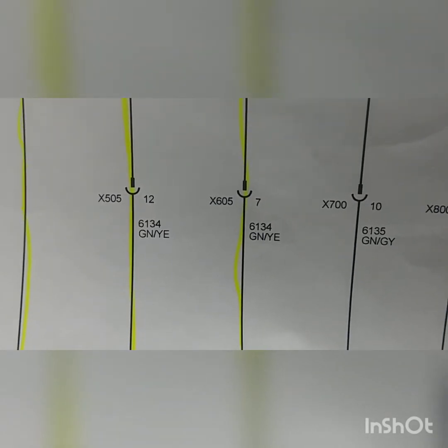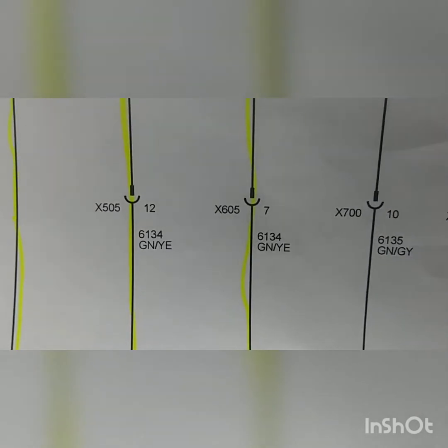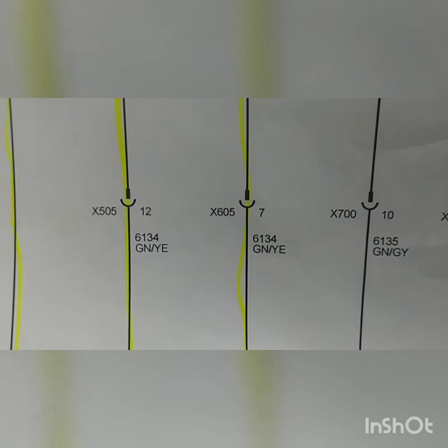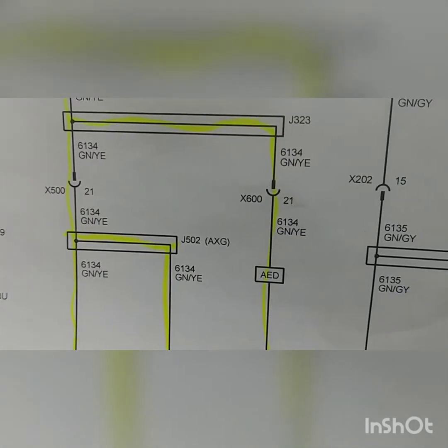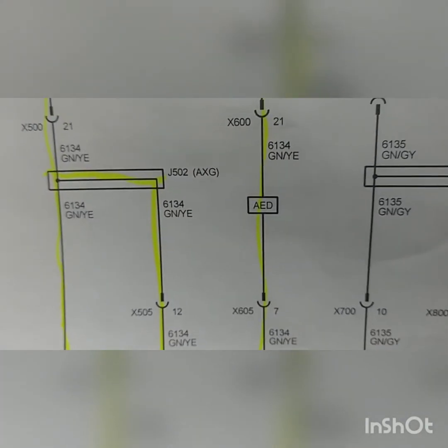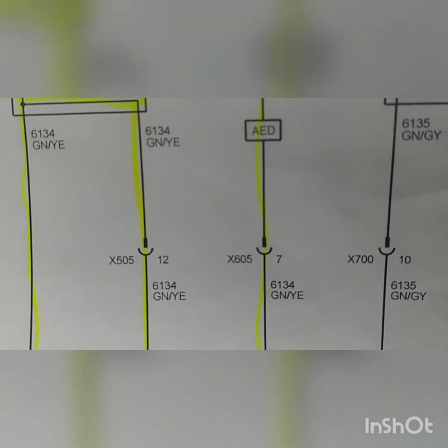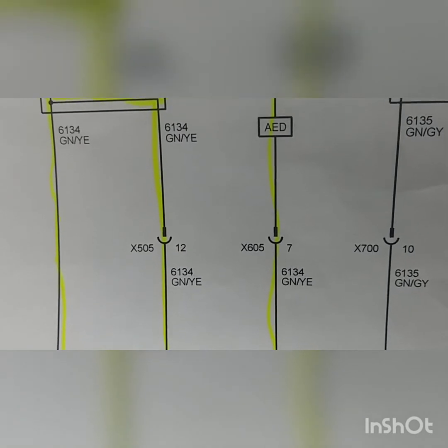And so anytime we had that connected, without knowing, even when we disconnected 600, that circuit running through, that voltage running through pin 7 on connector 605, was causing the LIN line to come down.